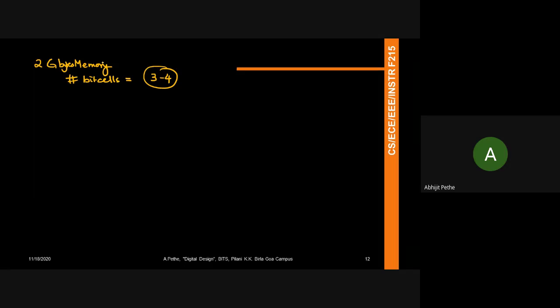So it is possible that the memory cells, suppose you had initially stored a 1 on the bit cell, some of those 1s might flip to a 0, right? Especially if the memory chip is old. Normally we spec a chip for say 5 years. So if you're running in your fourth year or third year of operation, you'll see that the failure rate begins to increase. So generally when we deal with memory, we always deal a lot with error coding.